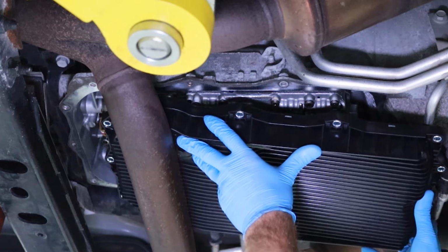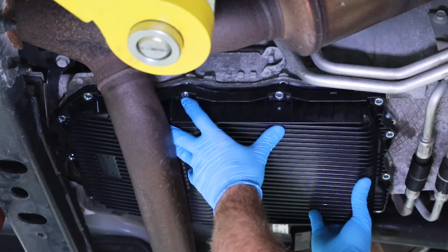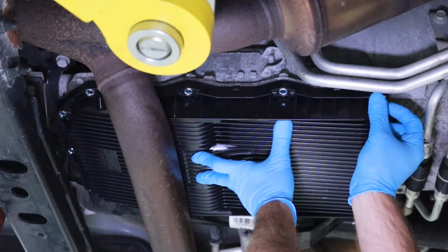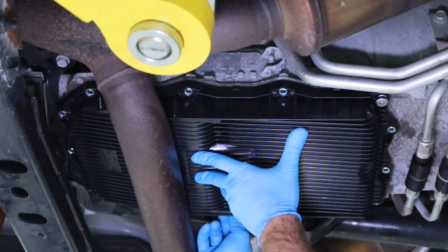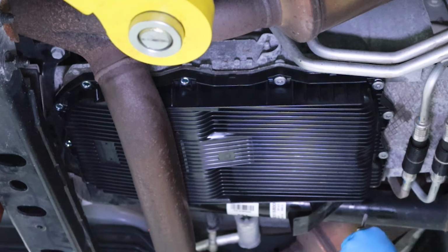First, confirm the transmission filter tube and valve body port are aligned. Apply a small amount of upward pressure to slide the filter tube up into the valve body. Once in place, align the rest of the transmission pan gasket mounting area and begin installing the new transmission pan mounting bolts.